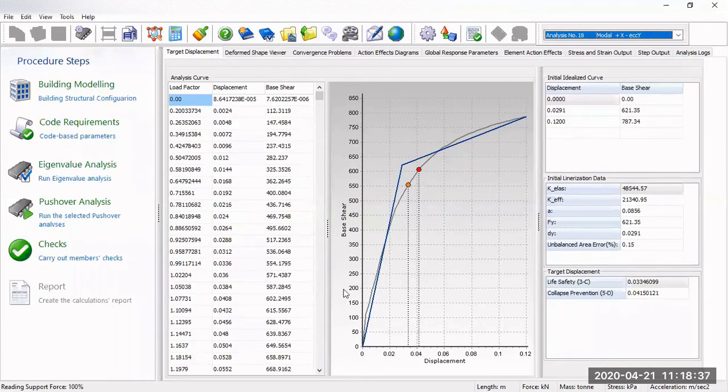What is shown in this curve here is the base shear, your pushover curve, your base shear versus the displacement. Okay, and also including the target displacement calculations for each of your limit states and also for your maximum. In this drawing here, there are 2 dots, one orange, one red. The orange color, representing this line here, is the target displacement based on the limit state of life safety. And the red color here is representing the limit state of collapse prevention. This is the value of target displacement we already calculated for you, and these are our limit state values.